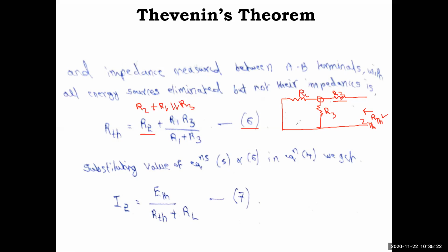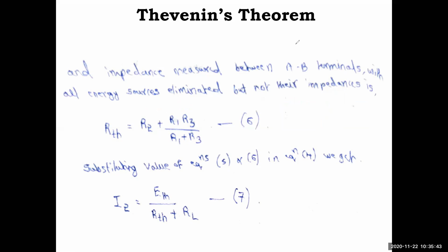These two circuits I have not done, so you can write them for your understanding. Here you cannot measure with current zero and all. We are finding the equivalent resistance by looking at how the resistors are connected. R1 and R3 are in parallel, and this parallel connection is in series with R2. Anyhow you can write. Now from equations 5 and 6, observe neatly here.